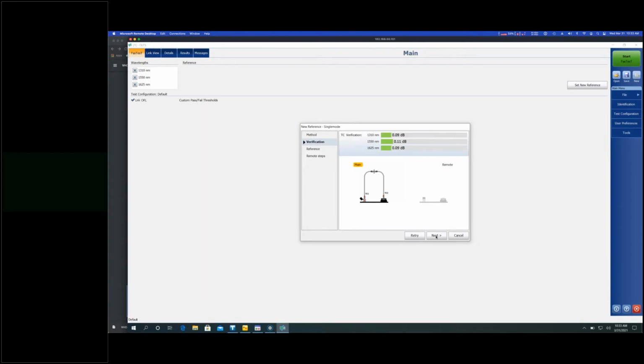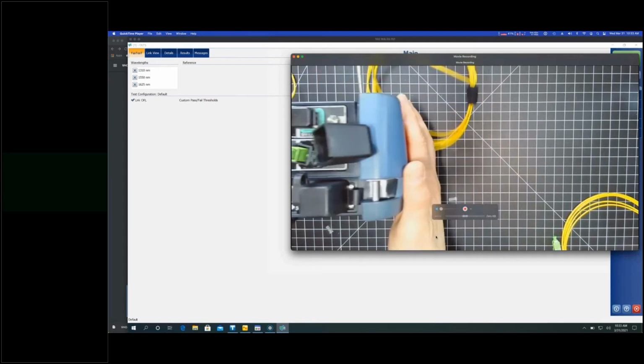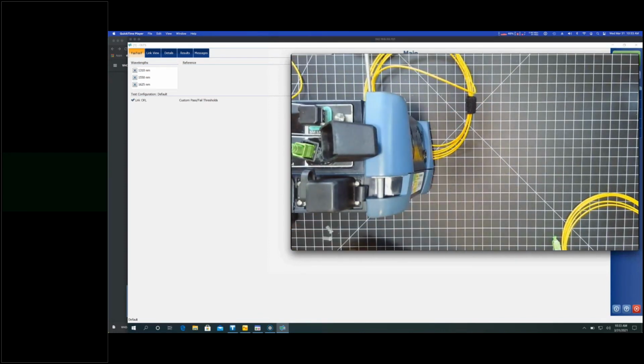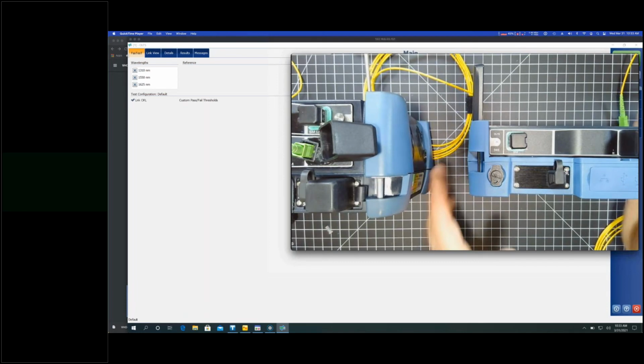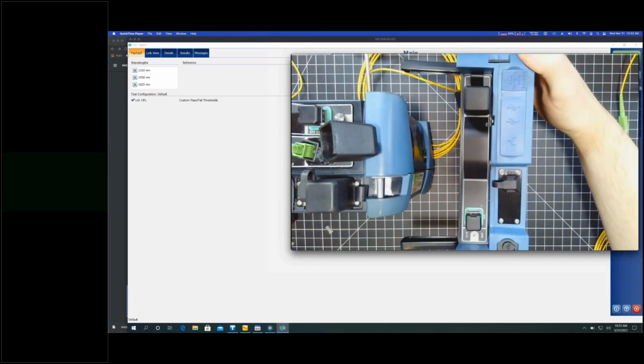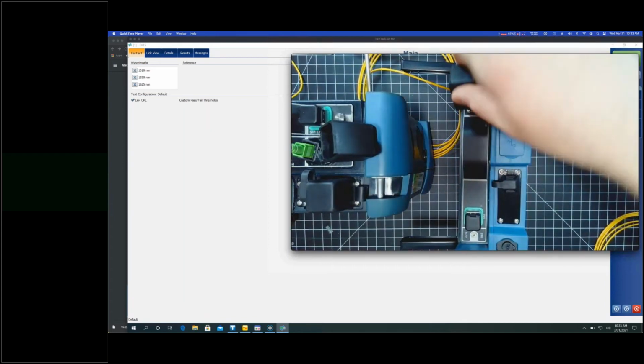Everything looks good on those cables. Now, I've got the other end of my test equipment, which in the previous method we did a power meter and source. And now on the other end, I've got a portable, a Max 945 with a source and a power meter connected to those.